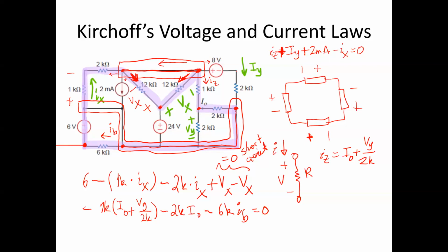The thing that you must be careful of is that you also have to add the current here, which, because it shares the branch with the 6 k ohm resistor, is also IB. And so you get a situation where IB equals a lot of terms minus IB, because we're summing outwards. And so that makes it kind of hard to find IB, because you get a plus IB and a minus IB in the equation and they cancel out.